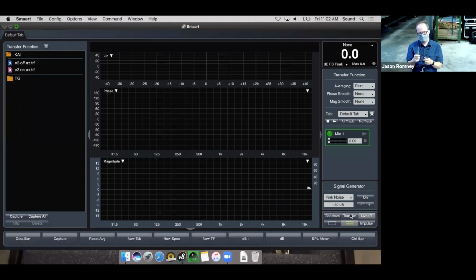So the best way to get a flat frequency response is to make it omnidirectional, to not try to make it a directional mic. That basically means sealing it all around, so you don't have any vents or ports on the side like you do with other ones. That tends to make it omnidirectional.